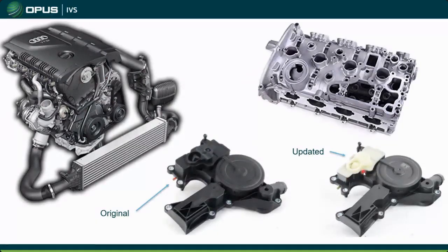Now, obviously, we would really do it by part number, but a quick and dirty way of telling if they've had the updated valve, which was actually part of a recall for a little while on some vehicles, where they actually recalled these vehicles to update them. It's an easy way to tell, because one of the major things that was done when you switched from the original to this updated valve was that you actually had to reflash the ECM, because this valve runs much lower crankcase vacuum than the original ones. They lowered it, I think, by about 100 millibar.